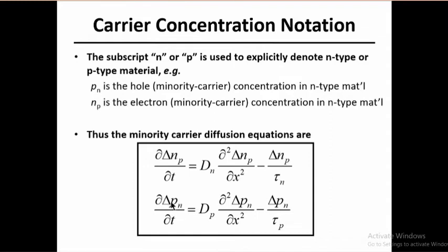Here I will be talking about minority carrier in the N material. So keep in mind, if I'm talking only about P material, I will say p_p times n_p equals n_i squared. So the product of the two will stay n_i squared, it will not change. And we will go into detail when we talk about the PN diode. On Thursday, we will start with the PN diode.